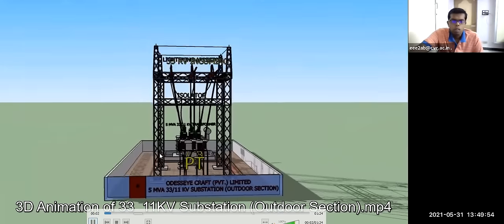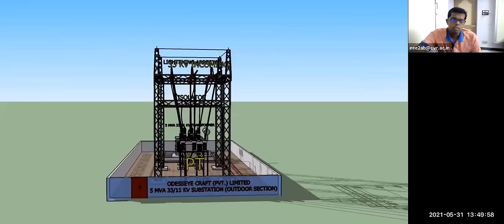It's repeating. So you have seen the circuit, like current transformer and potential transformer. Current transformer is for measuring the current, because the current in the power transformer will be very large, in mega amperes. It is not simple to measure, as you studied in your protection subject. If you design equipment for it, it becomes very big and very costly, and you can't directly measure that much current. So what we are doing is going for a current transformer, reducing mega amperes to some amperes, like 10, 15 or 20 amperes.